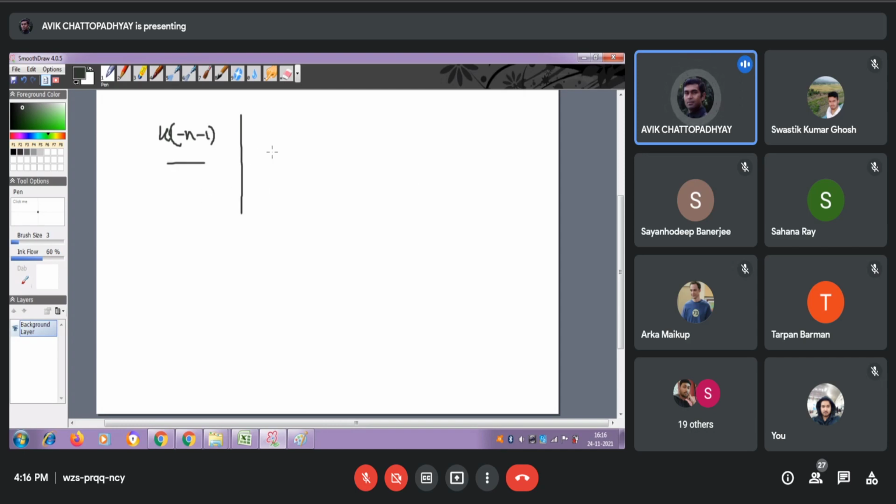The representation may be something like, suppose u of n plus u of, this signal has a very special significance, that's why I'm mentioning here, minus n minus 1. Please note, if you do this operation, you have u of n plus u of minus n minus 1. So what it actually indicates is an infinitely extended sequence. It's kind of a DC value, no? Extended from minus infinity to plus infinity.